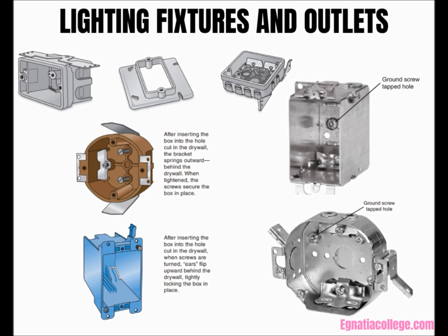Outlet boxes must be accessible, Rule 12-3014(1). Be careful when roughing in boxes for fixtures, and also when hanging ceiling fixtures to non-metallic device boxes. Non-metallic device plaster rings. Metallic device boxes. Metallic device plaster rings. Any non-metallic box, unless specifically marked on the box or carton for use as a fixture support, or to support other equipment, or to accommodate heat-producing equipment.